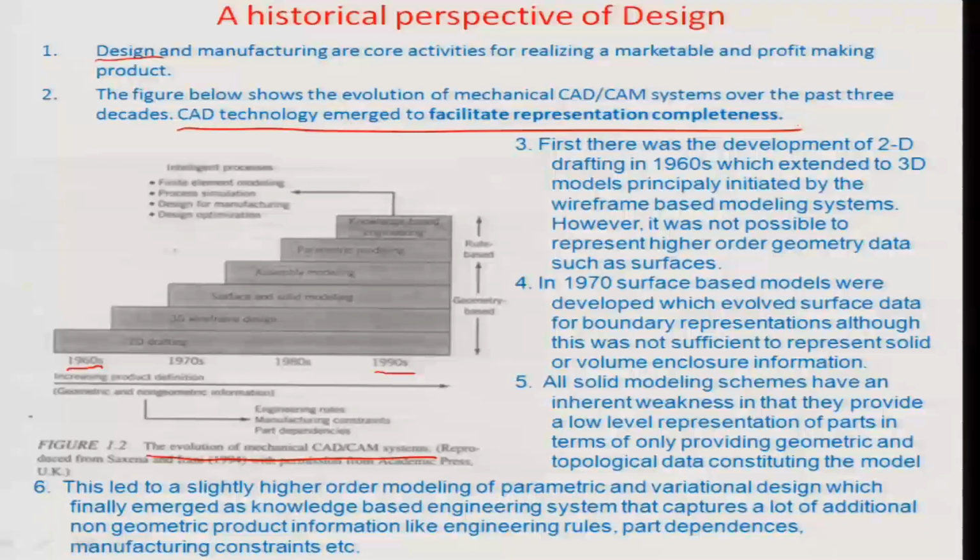So the first step in the history, if you look back in the 1960s, was the development of the two-dimensional drafting system, okay, which was extended to the three-dimensional models, principally initiated by something called a wireframe based design model. When we are going to do CAD, we are going to address what exactly is a wireframe design, but it's actually a pseudo three-dimensional representation of at least the edges of an object through which you can define the whole object.